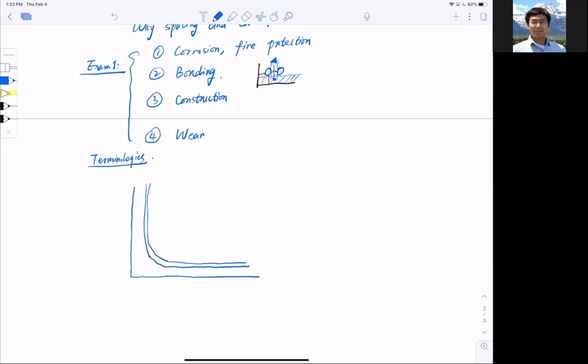Now to put the bars, naturally you would think I would put a bar here. I would put one bar here, and pay attention: when I draw the bars, I did not fit exactly the corner. It's somewhere on the bottom of the stirrups. So that's one bar, and of course this is in tangential contact.